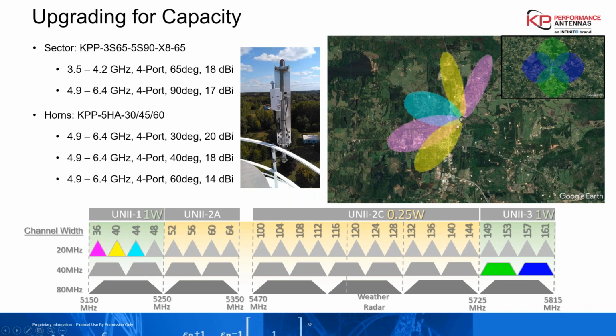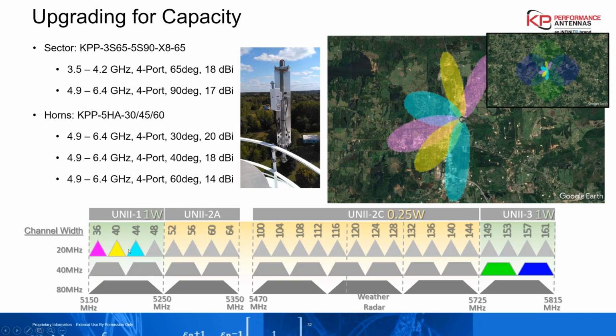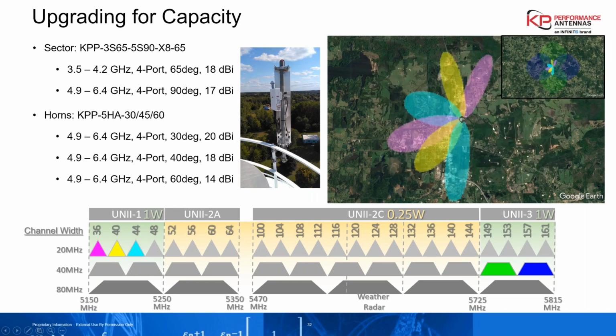Instead of having to worry about going back to back, you can worry about just having enough angular spacing between the two channels. So that's about, I don't know, 90 degree spacing between the two, and that's sufficient. So you can start reusing frequency. So now you're just on 3 channels, 20 megahertz channels, and you're going all the way around the town. But you don't care about over here, because you got a sector giving everyone coverage, and you don't want to waste more money. So that's kind of how you do your deployment.